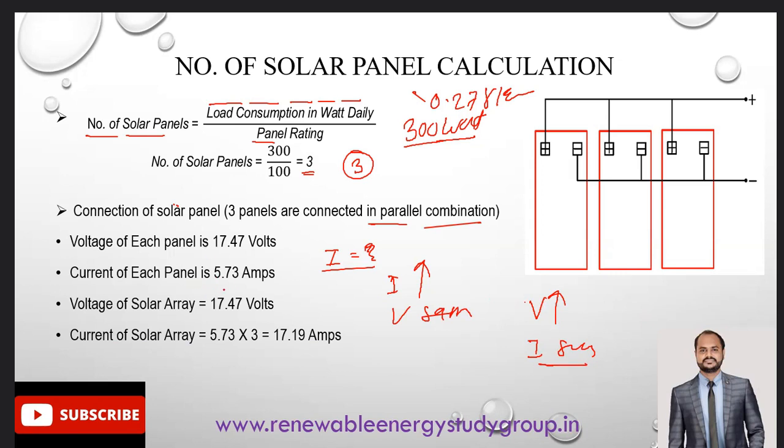So in this case, we keep the rated voltage the same, that is 12 volt on an average. As we know, the individual voltage of a solar panel is 17.47 volt. The current of each panel is 5.73 ampere as per the data sheet. When we are connecting the panels in parallel combination, their voltage will remain the same, but the current will increase. So 5.73 multiplied by 3, we get 17.19 ampere. This will be the final current that we are getting from this particular solar panel array.